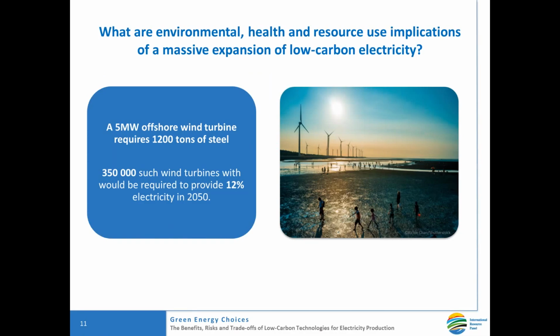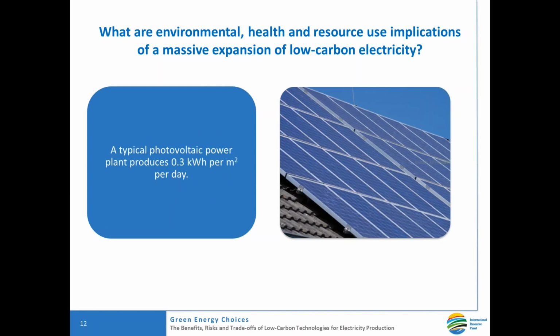So you wonder, going to a low carbon power system clearly represents a tremendous change, and it will impact the landscapes around us. If you think about a 5 megawatt offshore wind turbine, this is the large size of wind turbines being installed today. It requires 1,200 tons of steel, so that's quite a massive structure. 350,000 of such wind turbines would be required to provide 12% of the electricity by 2050, according to the IEA scenario that we have been utilizing.